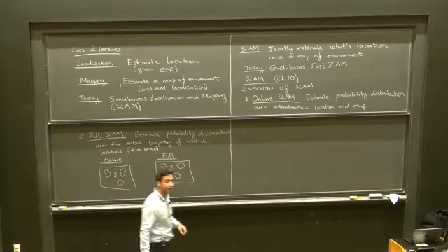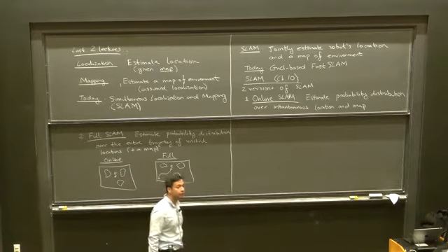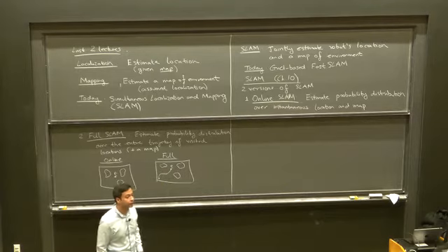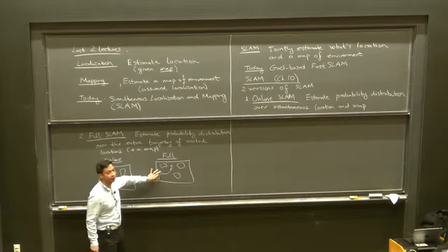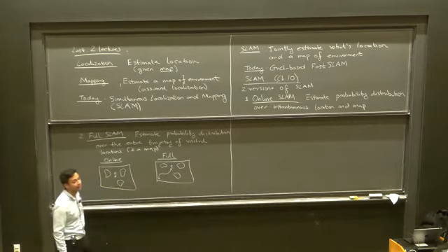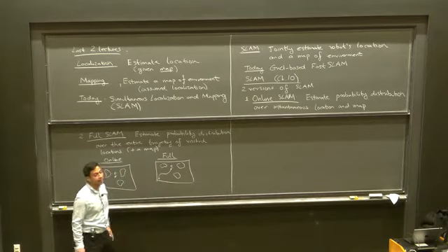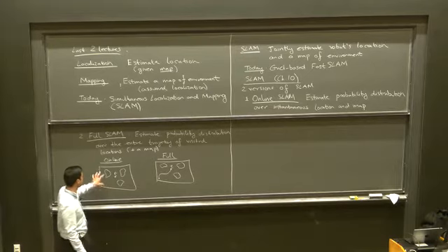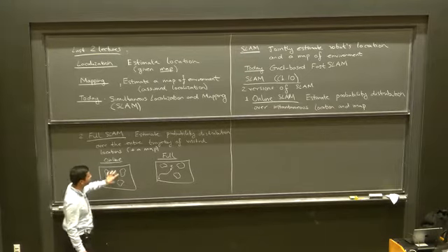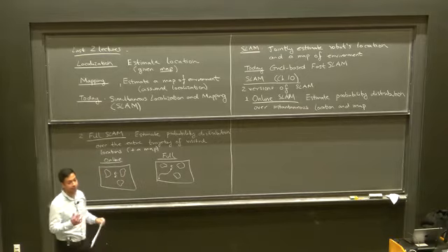Question? How much more accurate is full SLAM than just concatenating your previous beliefs? Yeah, so it can be more accurate to do the full SLAM version. We'll get to that later in the lecture. I'll show you some specific instances where doing full SLAM can get you more accurate estimates than just doing online SLAM. Yeah, I'll show some examples.